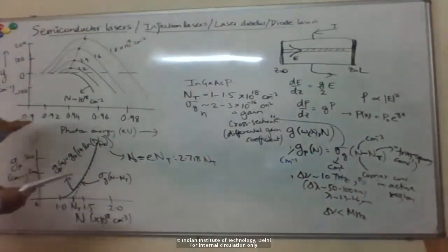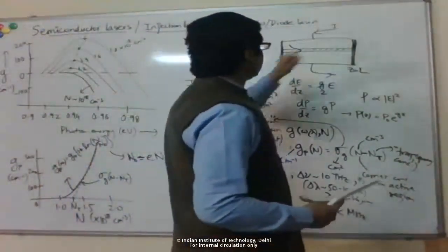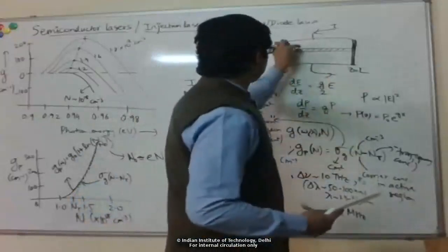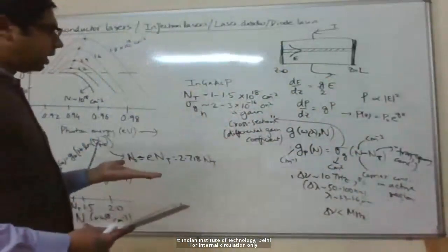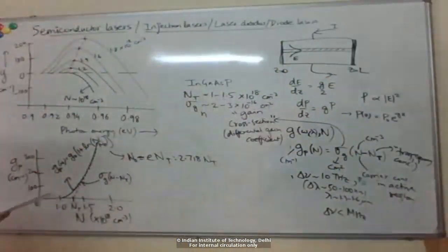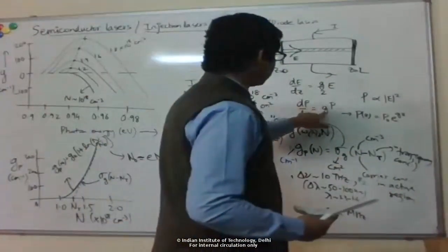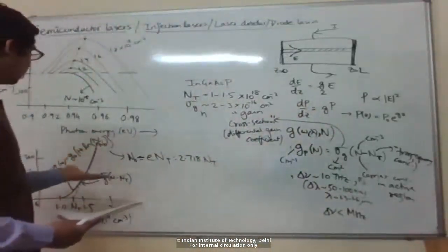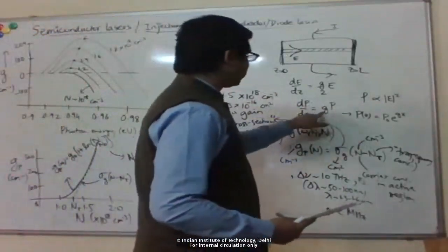So you can basically imagine what's happening. As we increase the current injected into the device, I'm injecting more and more carriers into the active region, which increases the radiative recombination rate and the stimulated emission going on, resulting in higher and higher G. So first of all, I increase the current such that I reach transparency, which is G equal to 0.